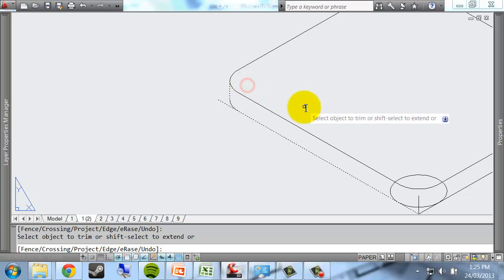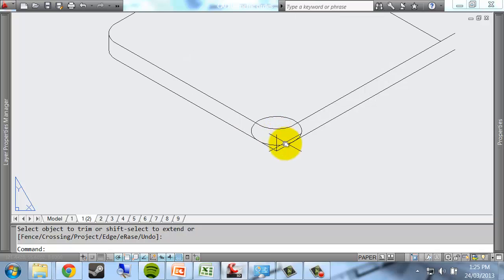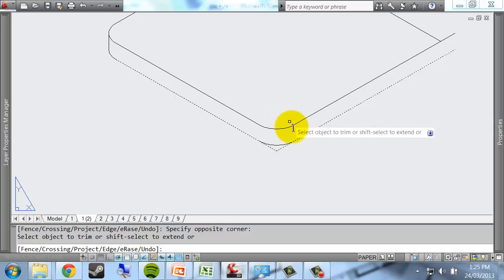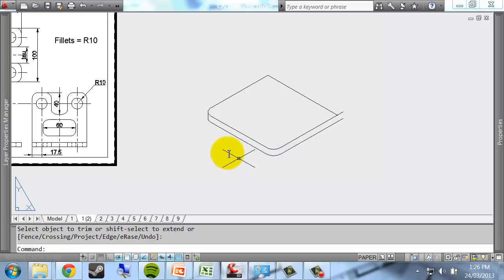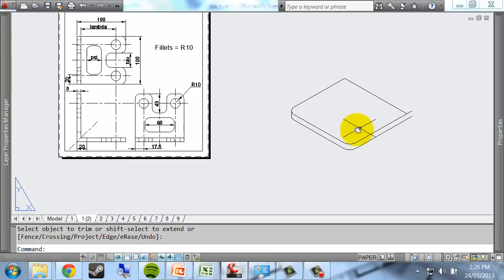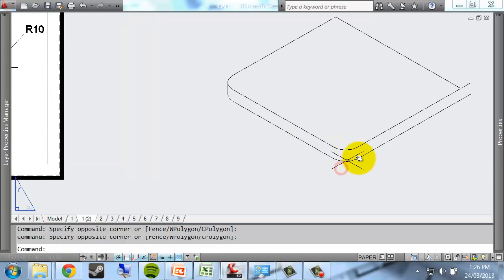I trim off that corner, grab this little piece of the arc and trim off that line, and in the front here I don't see a corner like I see up there with this straight line piece, so I need to trim off the back part of the ISO circle and then trim off the front part of these lines. So that's how I'd round up the shapes, and that's pretty much what you'll have to do for all of the rounds and fillets inside this shape. You locate a corner, you then draw an ISO circle on that corner, and then you trim it out so that you get a nice rounded curve like this.